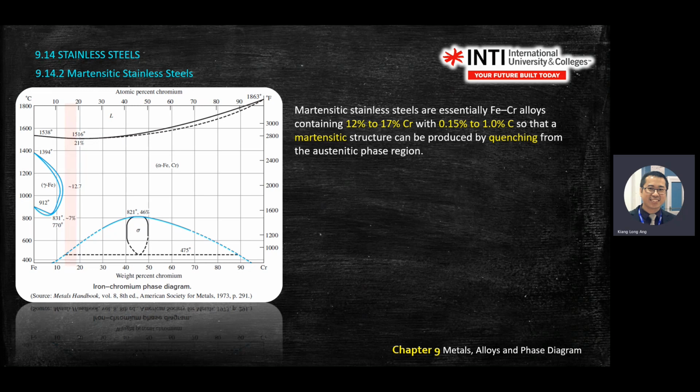In the phase diagram here, the bottom axis is chromium, not carbon anymore. Make sure you refer to the correct diagram. Don't always assume you'll get carbon for your x-axis. Read carefully. Although this one sounds like a big C, it's a C and a small r there, chromium. And if you see carbon here, normally it won't go past 6.67%. If you see a C here, normally the maximum value is 6.67%.